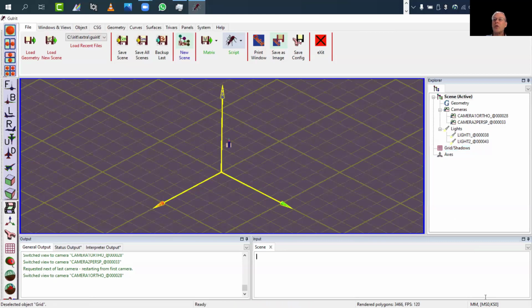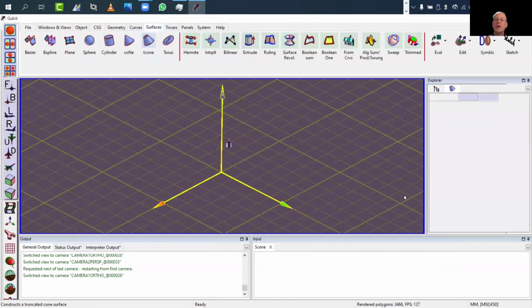So you can follow what they do with the mouse also with these messages on the bottom right. When I hover over geometries that are highlighted, this hover geometry will tell you in the middle properties like the XYZ location, the UV parameter in the parameter space of this geometry, of the surfaces in this case. Let's create a simple surface just for the sake of seeing this.